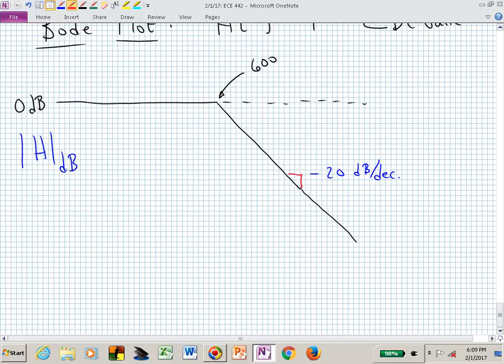So that's a kink trying to illustrate the slope. Thank you. So the slope of that curve is 20 dB per decade. Is that better? I shouldn't have had it in the same color as my minus 20, because it did look like 7 minus 20. But that's a slope symbol, and that's now minus 20 dB per decade sloping down, where this axis is now omega.